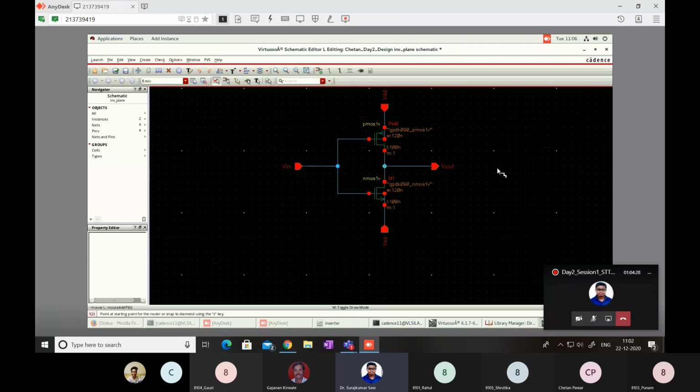Okay, fine. Now go to analysis, choose transient, right? In the transient, let's say we have to check for 5 pulses, as we have given a period of 100 nano. So for checking 5 pulses we provide 500 nano. Apply. Okay, this is the transient analysis. Now the last point: what you want to see as the output. Go to outputs, to be plotted, select on design. It will automatically come to your design window.